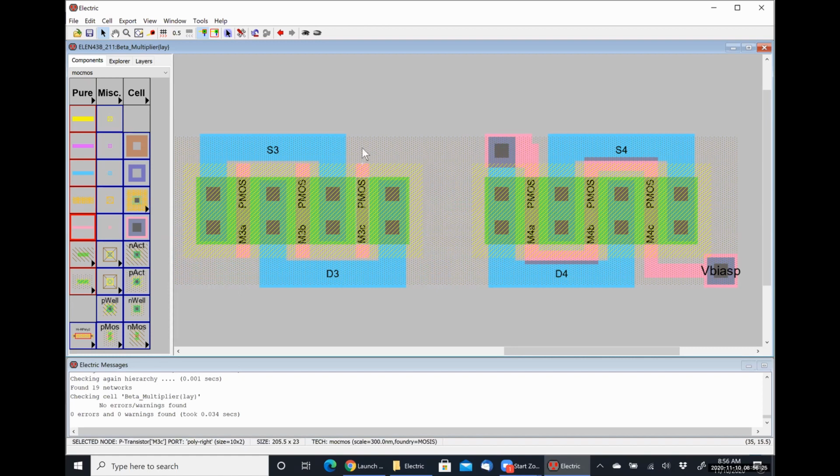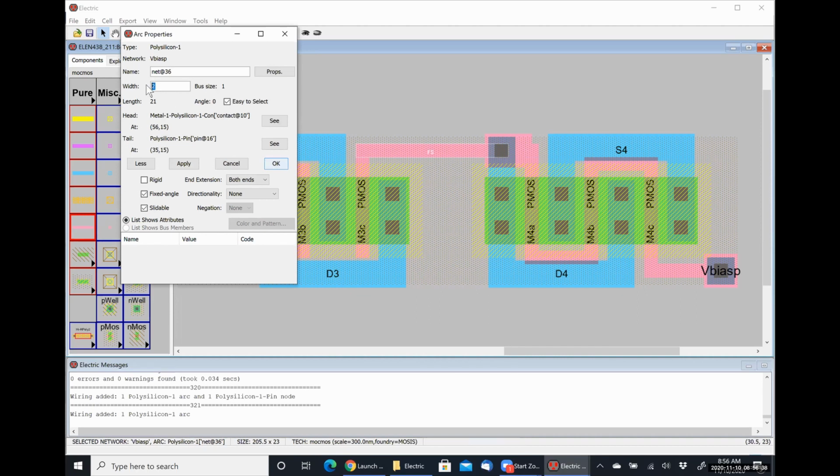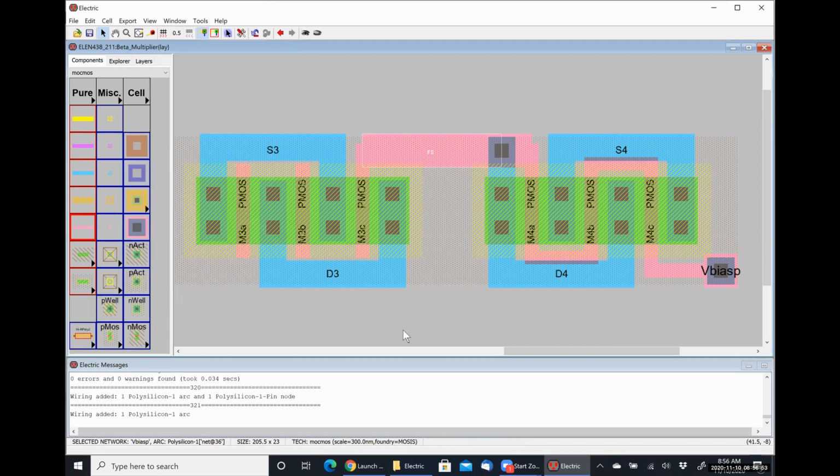And I think it'll be okay if I make it a big fat one like this. So I think we made the other one 5. Again, I'm just trying to minimize the number of squares so that we're having the least amount of resistance, so that we shouldn't see any appreciable voltage drops that screw things up too much.